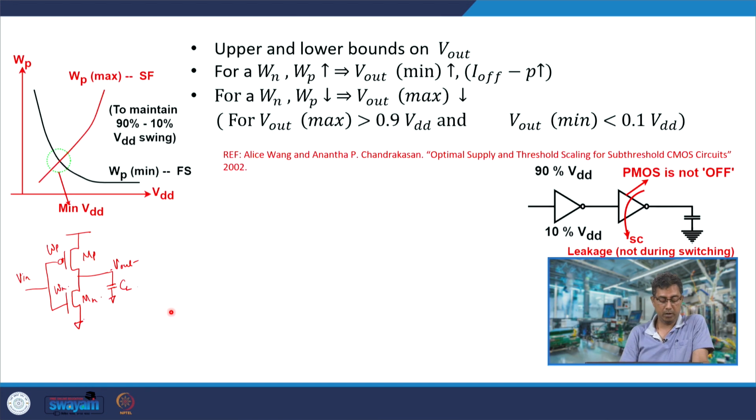So, we discussed implications of subthreshold swing S if it is varied. Suppose you keep on reducing the value of WP, what would happen? If the input is VDD and you reduce WP and keep Wn constant, then V out would finally reach near 0.